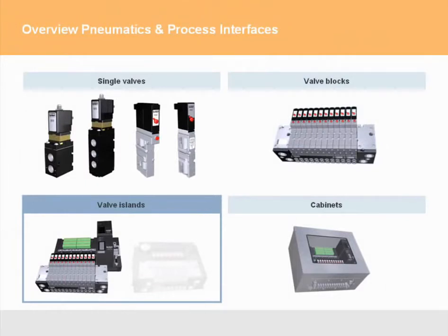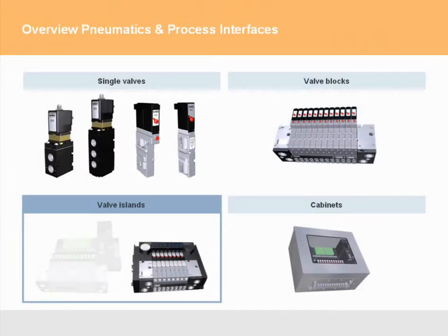Different to the Type 8640, the airline system Type 8644 can not only process digital but also analog signals. Overall, Type 8644 offers more functionality concerning modularity, data processing, and field bus techniques. Altogether, up to 64 valve functions may be combined together on one airline system.